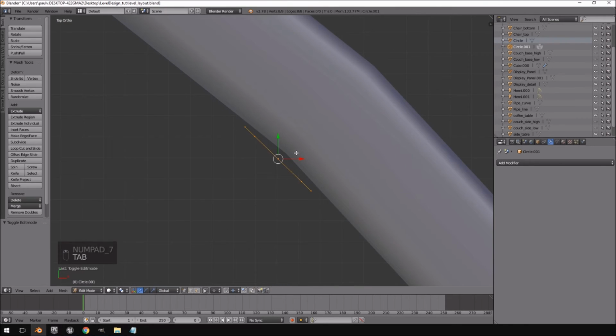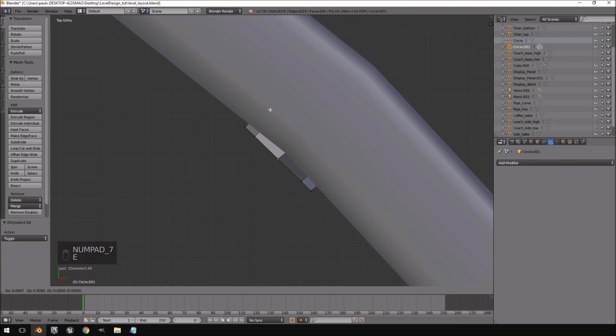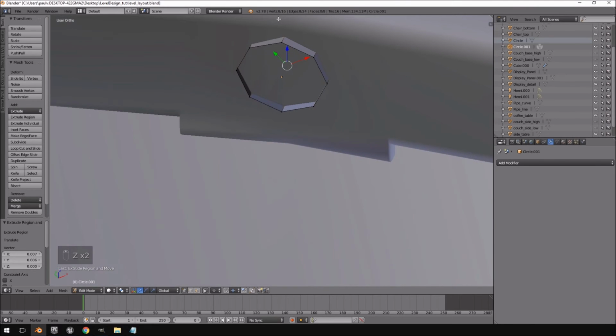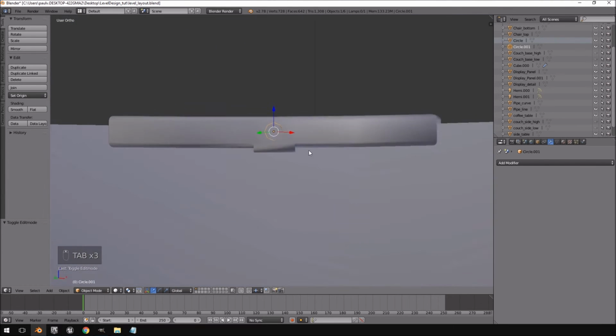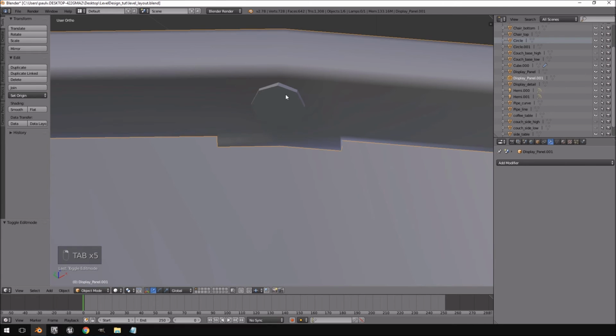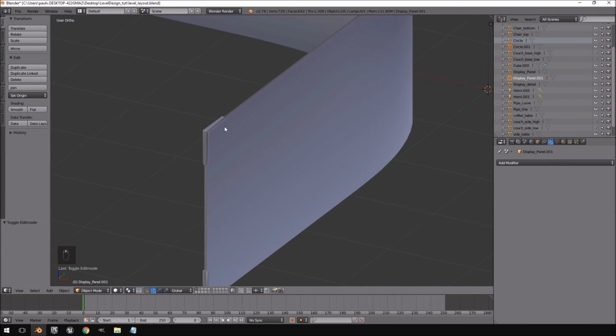And we're not going to have it, well, it's not going to just be on top. What we're going to do is extrude it so it goes through. We select these faces, hit E to extrude, and Alt M to merge at center. And there we go. And we've got our little red dot. And we can join all of these together. Okay, so let's first select that one, hold Shift and select that one. I am in object mode, and then right click, select those, and hit Control J to join them.